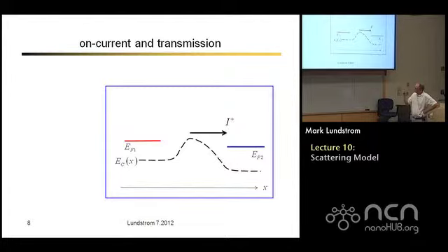The charge at the top of the barrier consists of electrons with only positive velocities under on-current conditions. Because all of the electrons come in from the source with positive velocities, they fill up the positive +k states. So we only have half of that Maxwell-Boltzmann distribution. What comes out is just T times what got injected in. No problem with that.